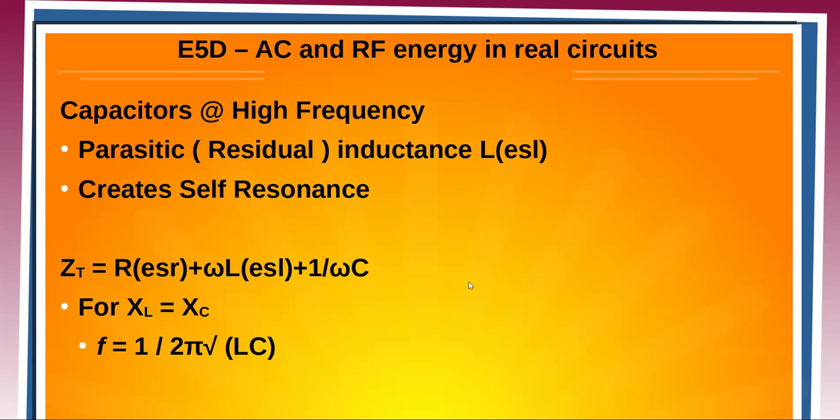Now, you also have what's called parasitic effects, both inductors and capacitors. In a capacitor, you can have parasitic inductance, where the leads, like you take a typical ceramic through-hole capacitor, it's got two metal leads on it. At high frequency, those are inductors in series with the capacitor. So there will be a frequency at which it's resonant. It's a series resonant circuit. And again, we have the resonance formula. So we call that self-resonance. You have the same effect we'll talk about next on an inductor, where you have parasitic capacitance between the windings. So it will be a parallel resonant circuit at a certain frequency.